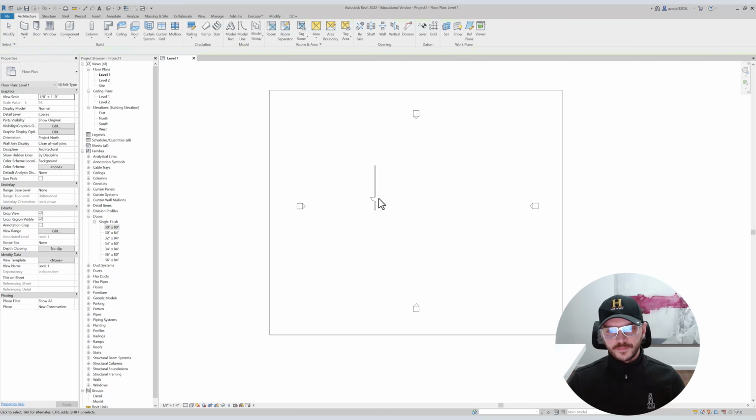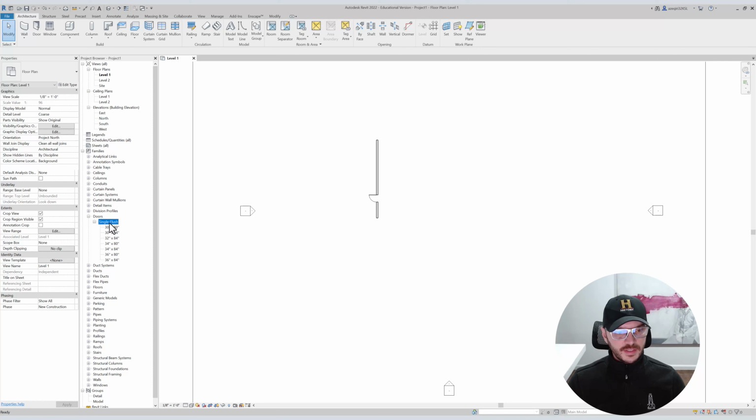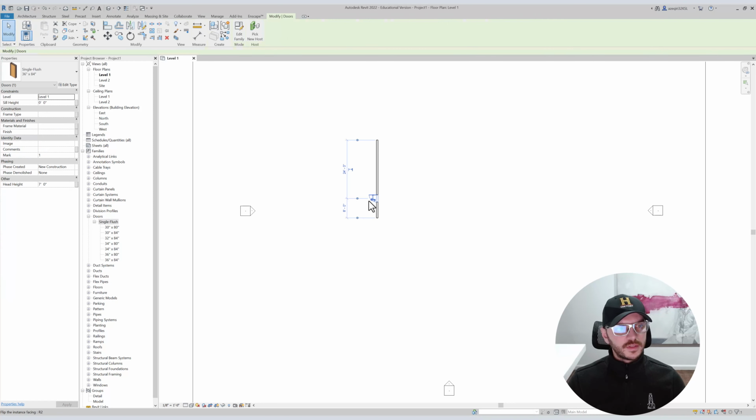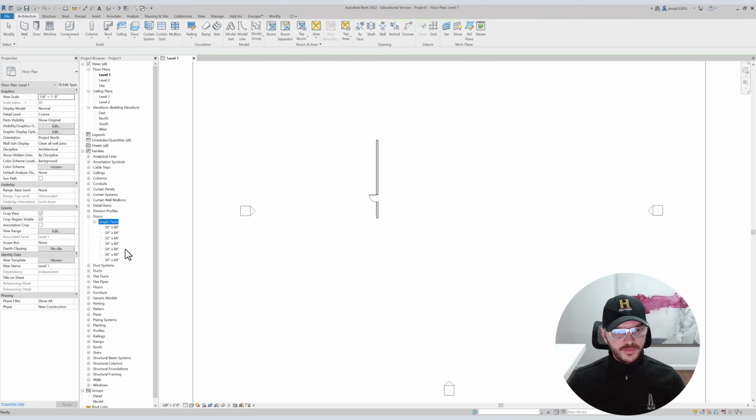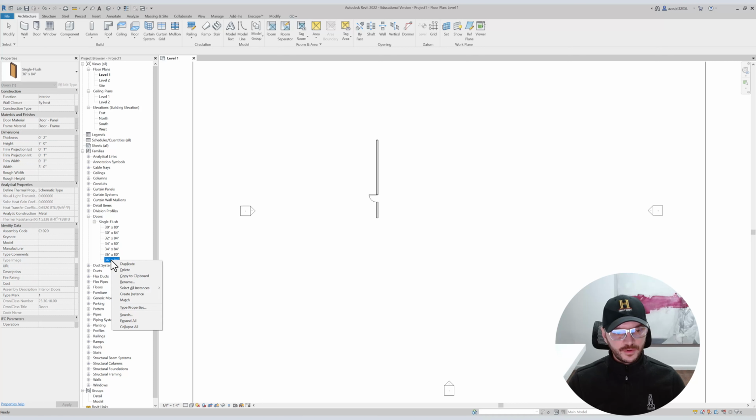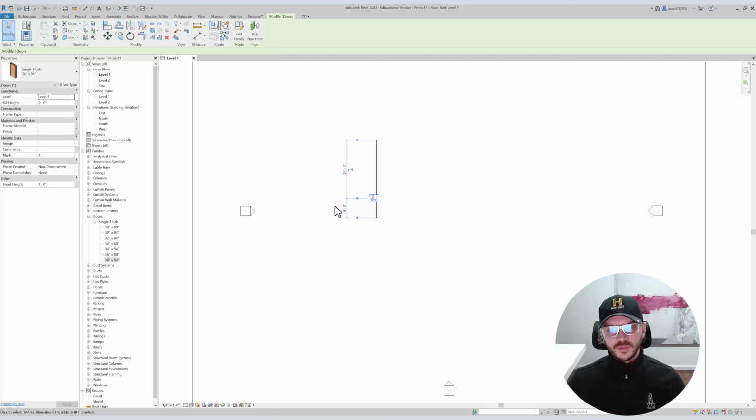All right. So as we can see, I can go into here. Let's not guess. 36 by 84. So if I go into here, 36 by 84, I do a select all instances in entire project. It will select all instances in entire project. And then it'll give me a count here in my properties bar. So it'll tell me, hey, we're selecting one of single flush 36 by 84 door. And then these are its properties.